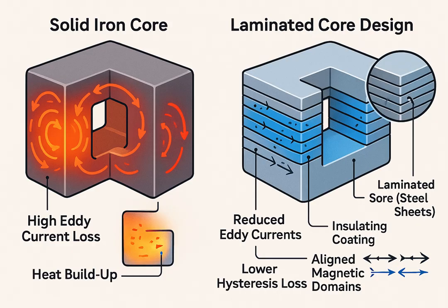These are circular electric currents that swirl within the bulk of the iron core, perpendicular to the direction of the magnetic field. These eddy currents have two main downsides. They generate heat inside the core, wasting electrical energy in the form of thermal energy. They reduce the transformer's efficiency, especially in high-frequency applications.